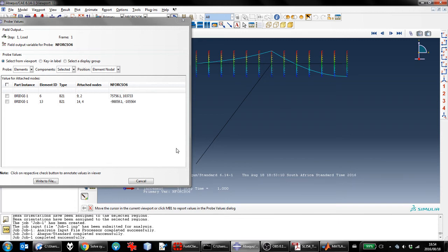Right, so obviously you could save this to a file, you could do loads of things with it, but the test actually just said draw the shape. So I would at this point just take my pen, write down these values. Again, the bigger value is the one of interest there at the midspan, and then draw your bending moment diagram.